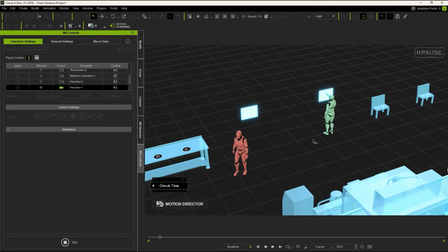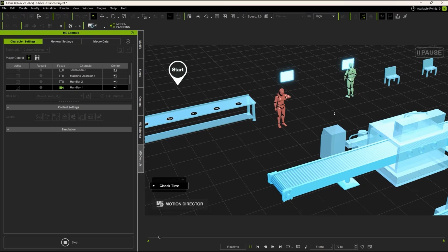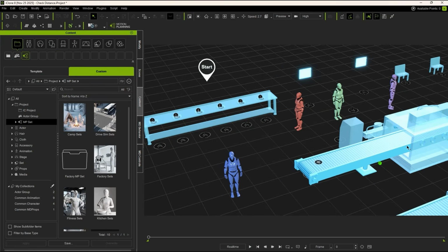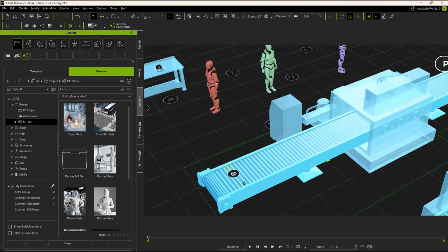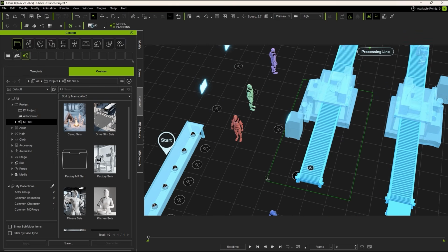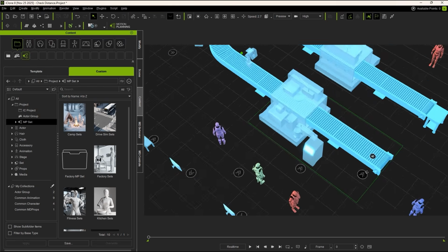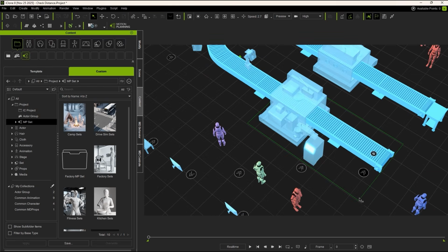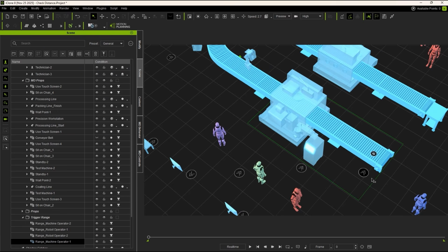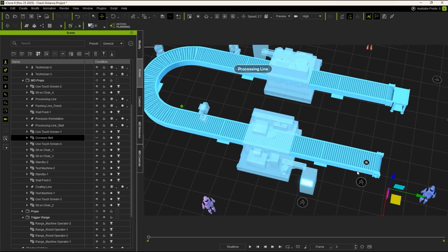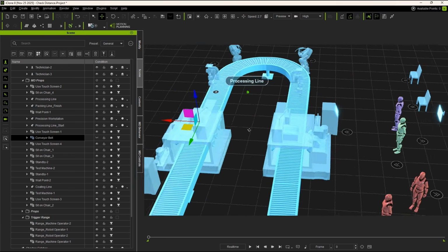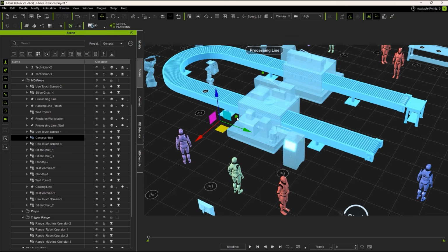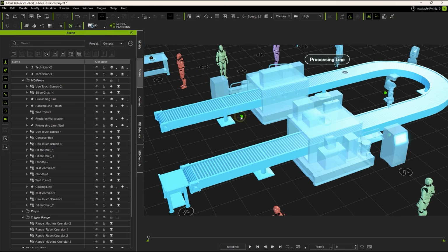This is where the check zone node comes into play. It allows accurate detection of when the work is truly finished. This works because there is a trigger zone set up in the scene. By combining this trigger zone with the check zone node, we can easily detect whether one or multiple objects are still inside the zone. Once all placement points on the conveyor belt have exited the trigger zone, the worker recognizes that the task is complete and is allowed to enter idle mode.